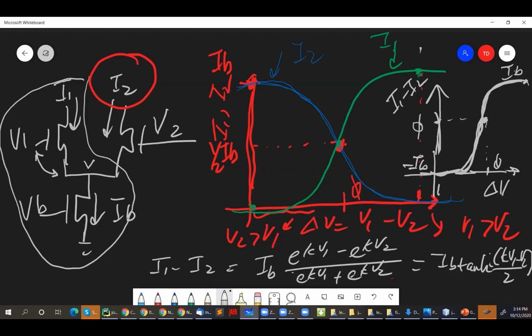We set the VB such that the VGS minus VT is about something. Yes, you're right in the sense that even if you set VB high enough so that this transistor is operating above threshold, say you set the VB to 1.2 volts, so clearly above threshold, the current that flows through this transistor is still dependent on the fact that you can consider this transistor to be in saturation, right?